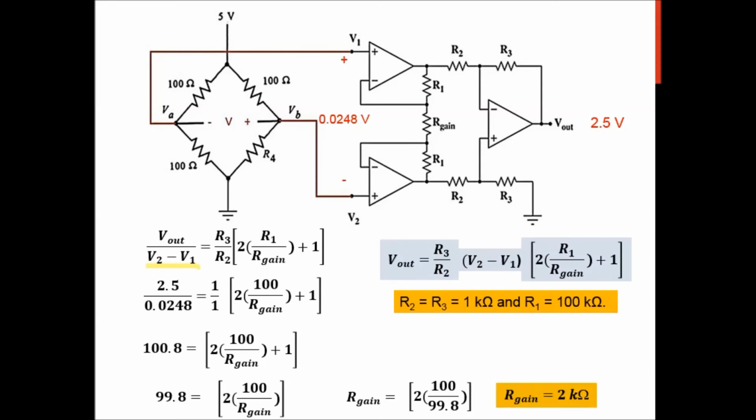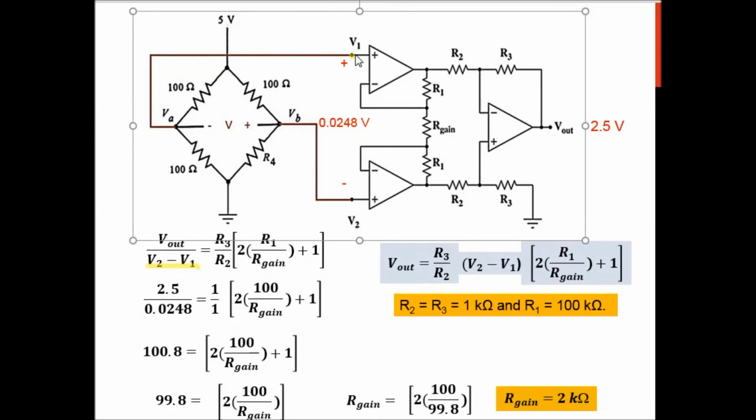Okay, so that is the end of the signal conditioning under amplification using op-amp, and mainly the final exam will ask about differential and instrumentation amplifiers, because those are the common amplifiers that I use with sensors. However, the main important thing you need to remember is the two rules of your op-amp. There are no currents into the op-amp, and the voltage at this non-inverting node and this node must be the same. So those are the two important characteristics of your op-amp.